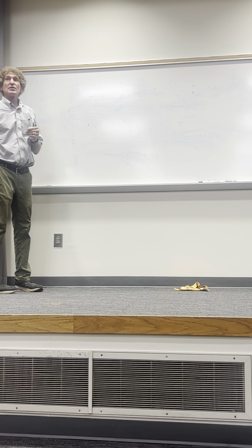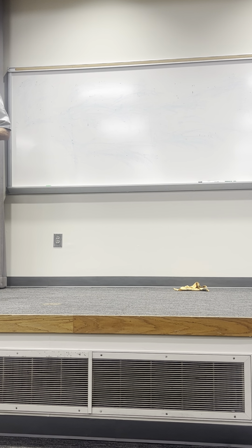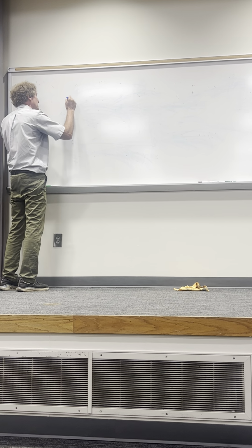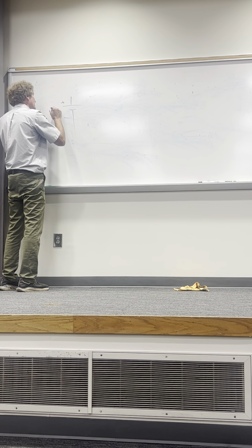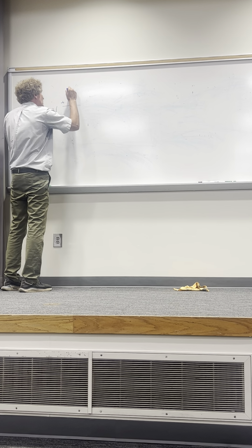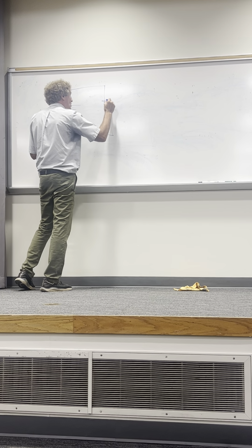All right, next we're going to do resistors that are in parallel. Now remember, with resistors in series, the hallmark is the same current goes through every single element, right? With resistors in parallel, it'll have the same voltage across it. Let me give you an example, and I'll show you how to do it. So, if you have a voltage here, V, and let me know if you can't see it, I'll draw it larger. And now I'm going to put a resistor here, R. I'll call it R1.